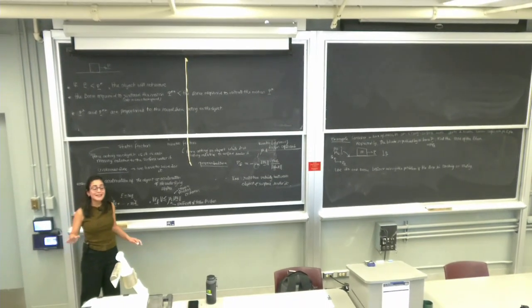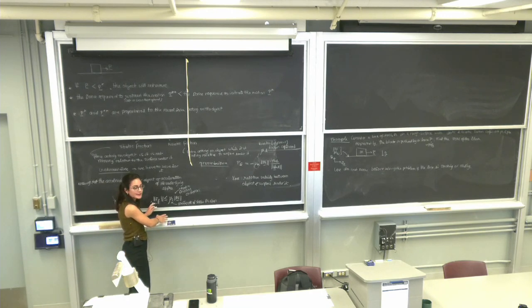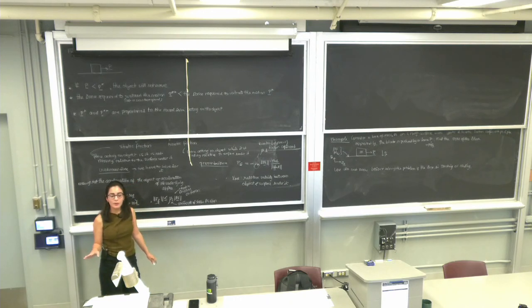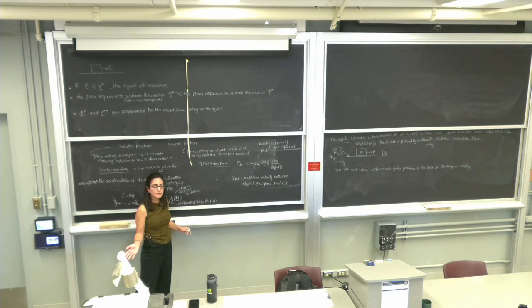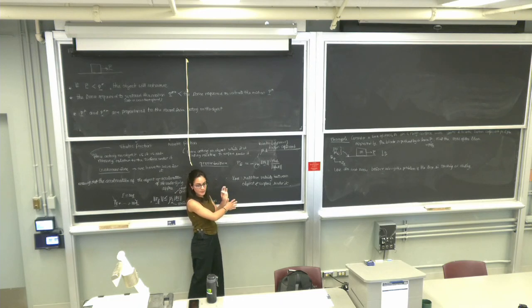So friction is indeed going to be static, in which case, which criterion needs to be satisfied? The static friction criterion. If it is indeed satisfied, then the friction is static and we've solved the problem. If it's not satisfied, then what do we do? Our assumption was wrong and friction is kinetic and we have to prescribe friction and solve it again.